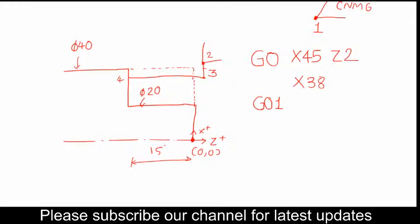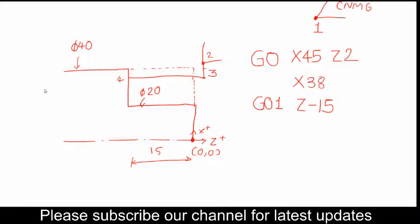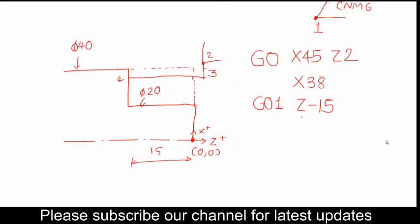Now, what would be the coordinate of point number 4? That point would change only in Z, which is Z minus 15. From here to here, at this location Z is 2, at this location Z is 0, and at this location Z is minus 15. But in the previous line, what did we write? We wrote X38. So X38 will remain as it is, and only Z will change, that is minus 15.